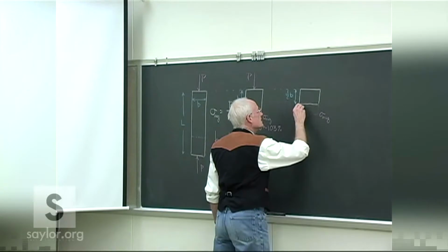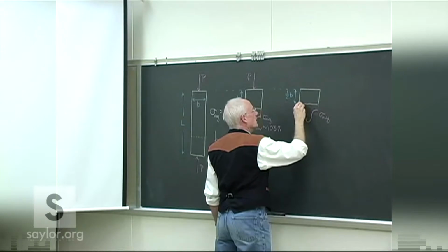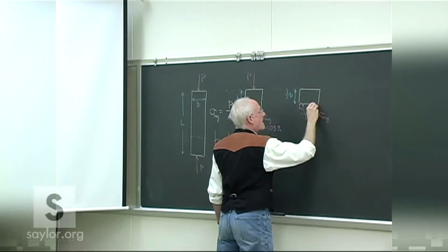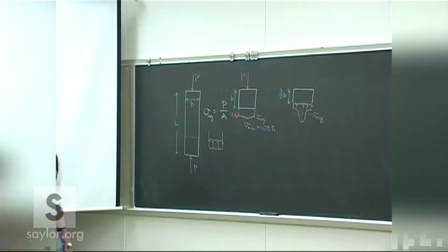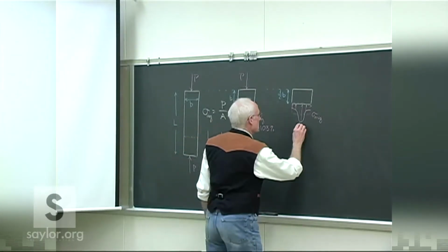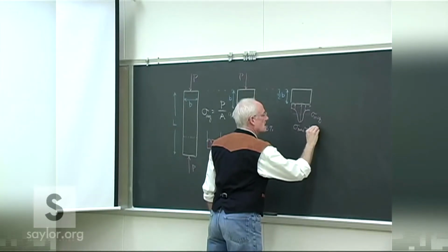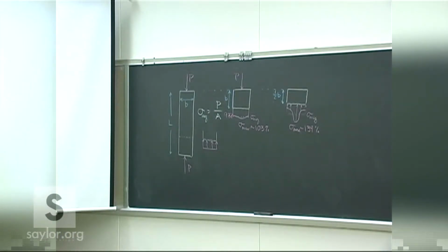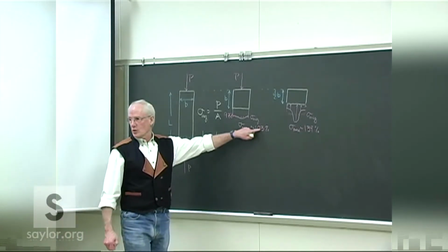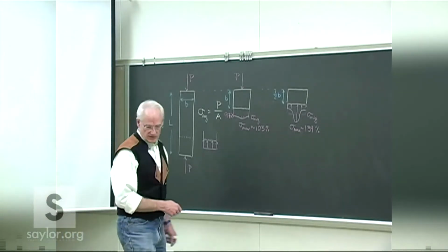The real stress distribution is a little bit more severe. Remember, this is a point load. And now that maximum is about 139% of the average. So things are getting more severe at the end. This isn't negligible. 3% we don't have to worry about. 40% you might have to start worrying. And this is part of the reason we put in these factors of safety.